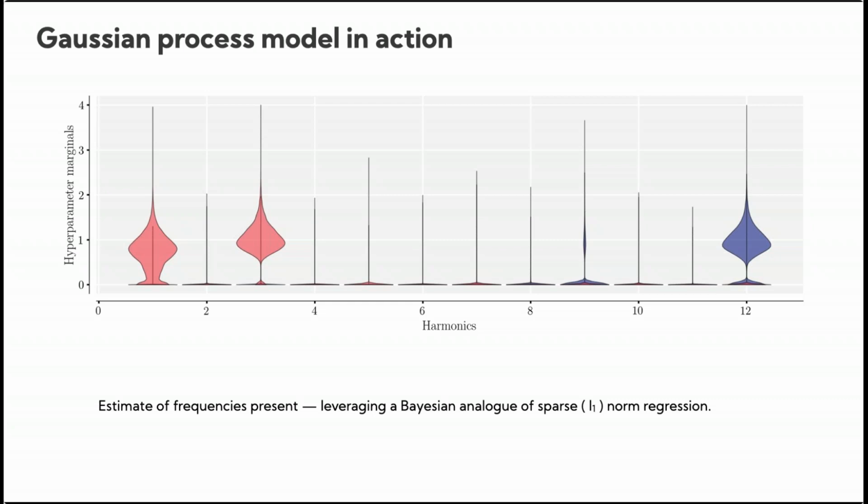So what we typically do, and in full disclosure it's not as rigorous as it can be, is based on an estimate of the imprecision for each probe, effectively a sigma value. For each plane we'll have a slightly different sigma, because if you measure temperature at the back end of the high pressure compressor, that uncertainty is very different to temperature you measure downstream of the fan, just because the instrumentation is very different.